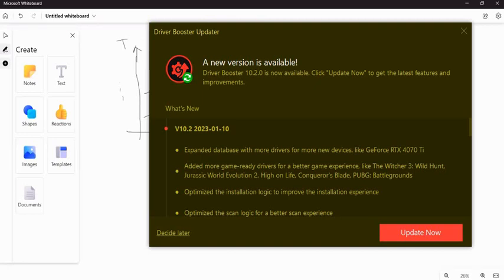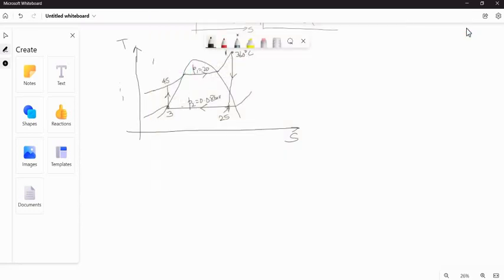So first of all, now we will see, enthalpy values are very important. We are going to use the H value from the steam table, and then the S value. What is H? Enthalpy. What is S? Entropy. Then from the steam table, I am going to refer to the steam table. So you have to keep the steam table with you, then only you can work it out.